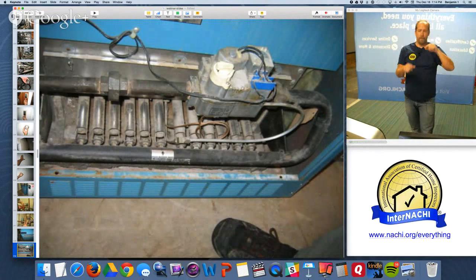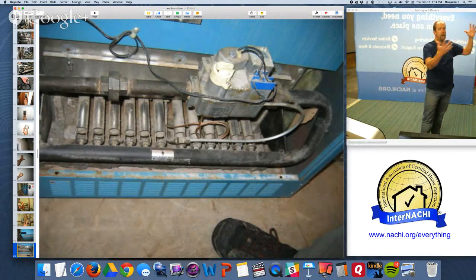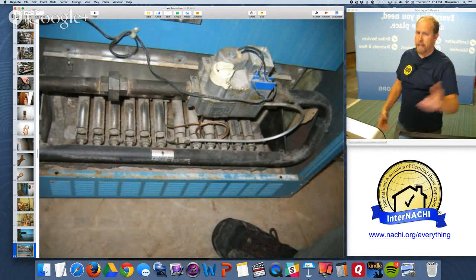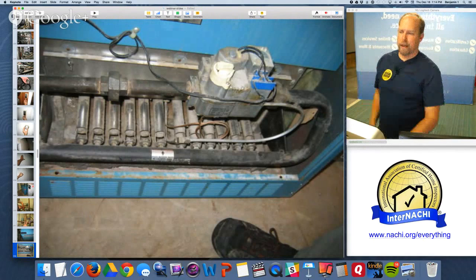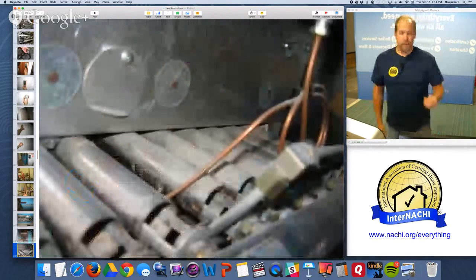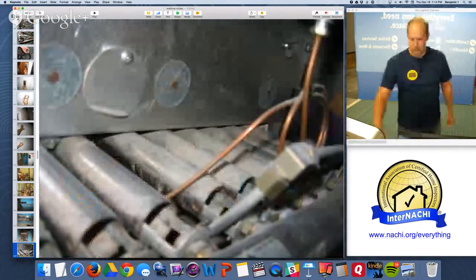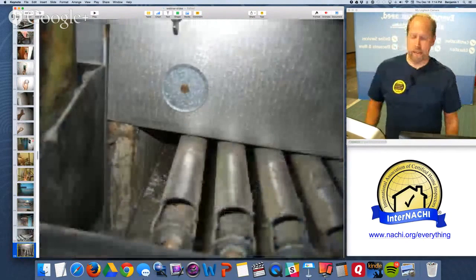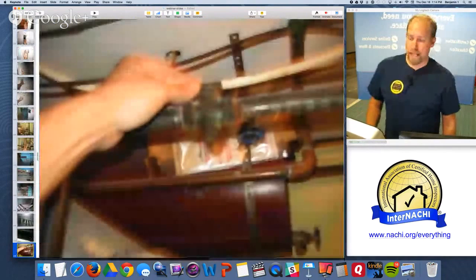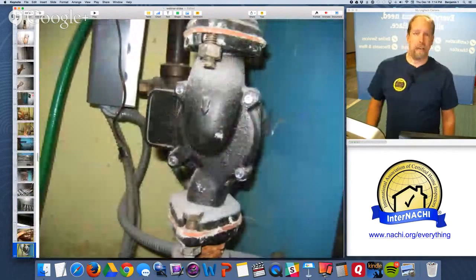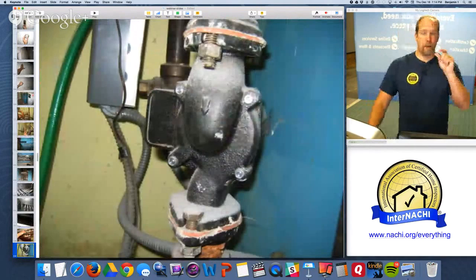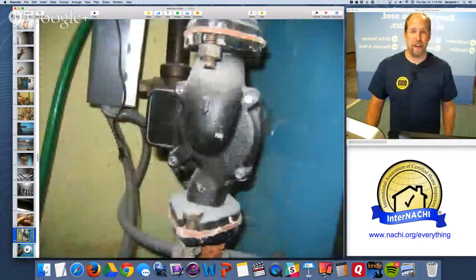So you turn on a valve, the water's circulating, a valve opens up, turn on a thermostat and a valve opens up, and that water then flows through. As it flows through, it's going through a radiator, and it's releasing its energy out. And it comes back cooler to be reheated by the boiler again. These boilers get really dirty, especially oil-fired boilers. Gas boilers need to be cleaned, and this one hasn't been touched in many years. I like to look at the flame color if I can, or the service record. If it hasn't been serviced in the last year, I call it out.